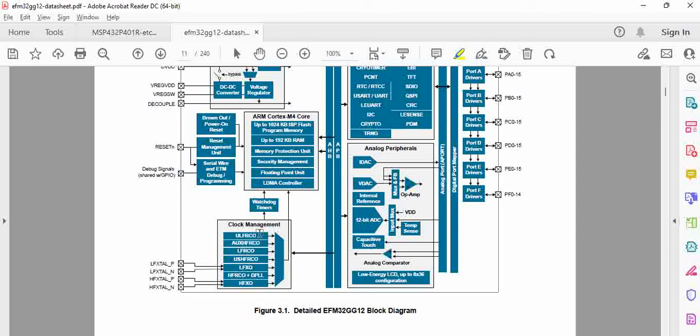The major difference is, if you are new to microcontroller usage, or new to connecting these kinds of oscillators, and you don't need too much stability of the clock, if you are okay with a very slight variation, and you don't need exactly a stable clock, then you can use an internal oscillator for different ranges of clocks.